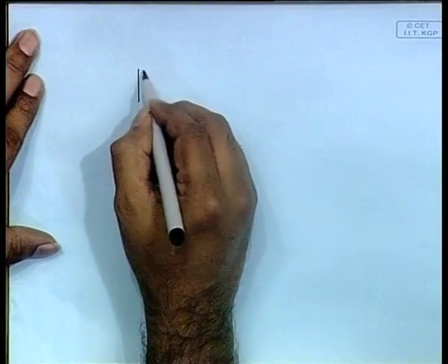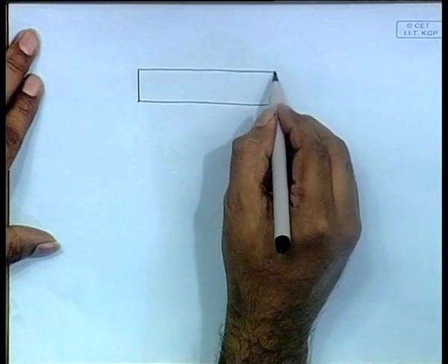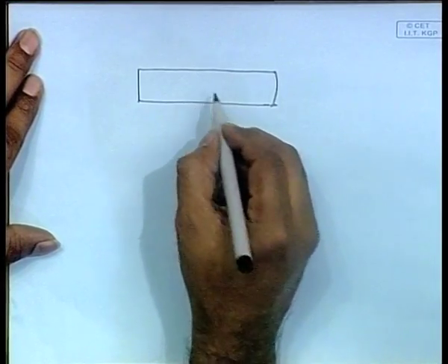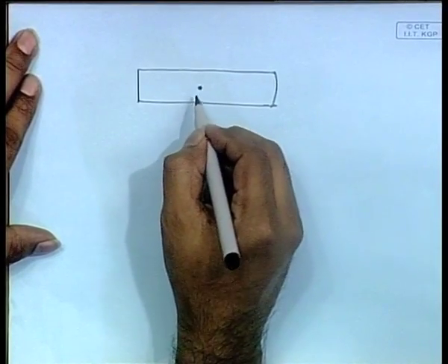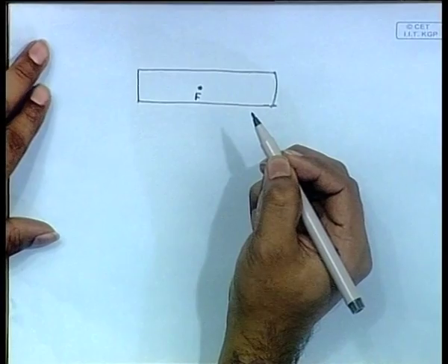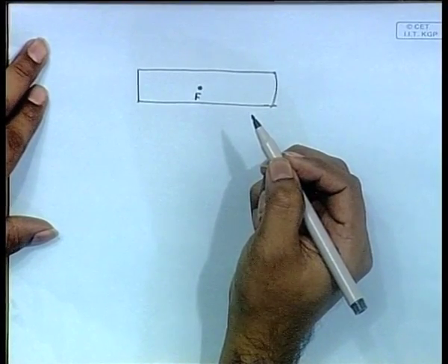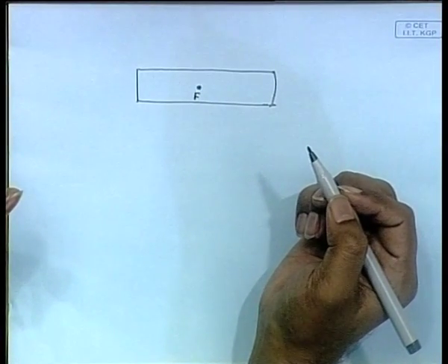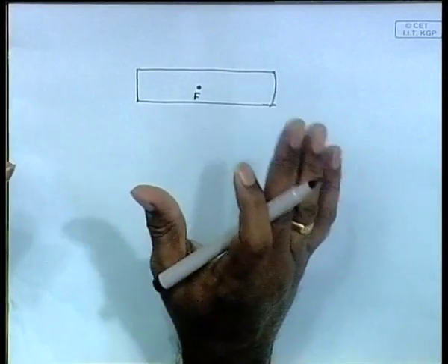Let's suppose that the plan view is like this of the ship. Therefore, somewhere here you have the center of flotation. Okay. Now, depending on this center of flotation, we always say that the ship trims or moves. Everything we have done about trimming, whether it is trimming aft or forward or parallel sinkage, is about the center of flotation, not about any other center, not even the LCG of the ship. It is about the center of flotation of the ship.